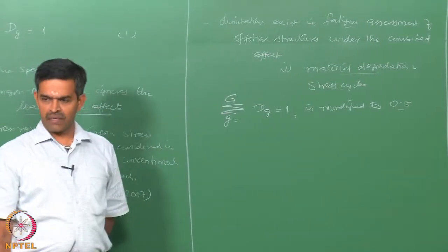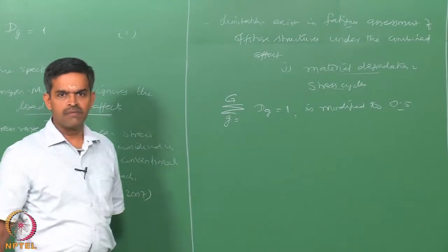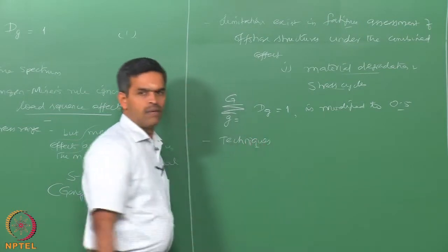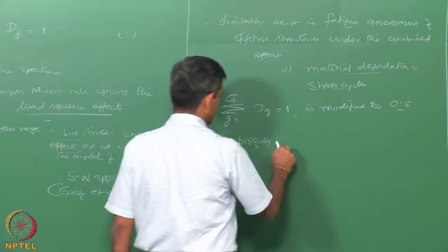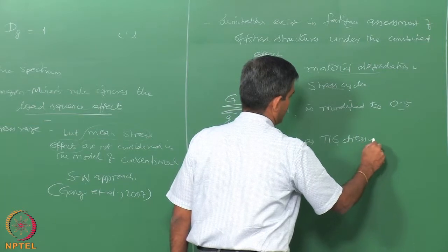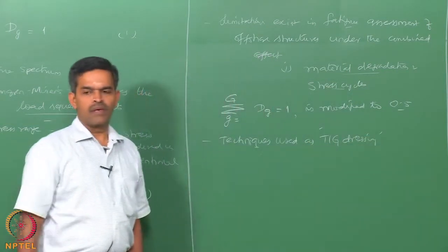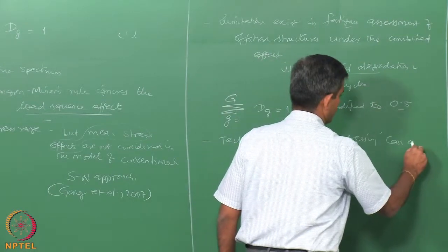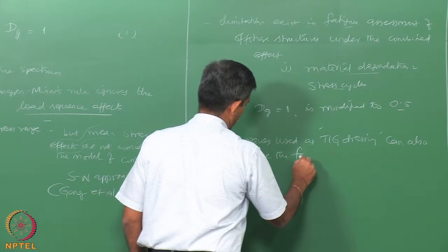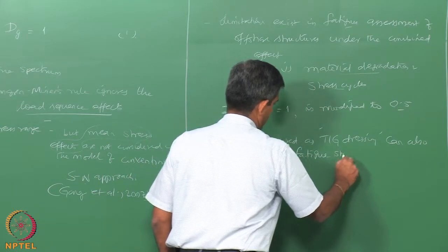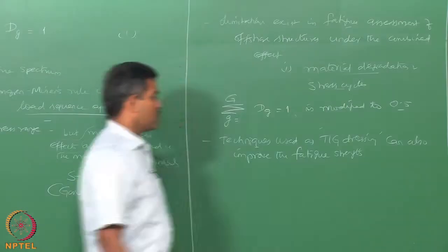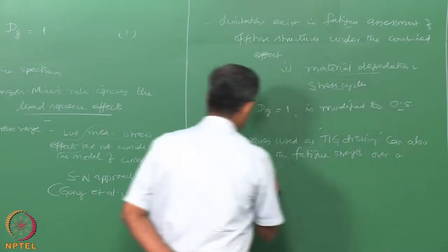Interestingly, there are other factors which can also affect the damage assessment. For example, the techniques used for dressing, TIG dressing we call it, can also improve the fatigue strength over gas welded specimens.